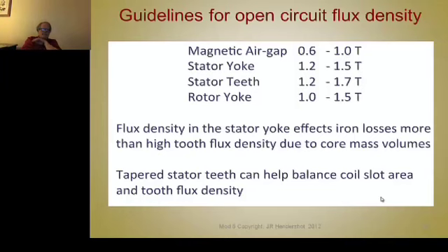Then I asked people in the class what kind of numbers they use in their company for the motors that they design, and boy, they give me all kinds of numbers all over the place. I'm surprised at the number of people that will run their flux densities up to 1.7, 1.9, 1.8 in the teeth and the yoke. I'm really surprised at that. When we study materials and look at the BH curves of materials, I'll show you the price you pay in ampere turns to do that.